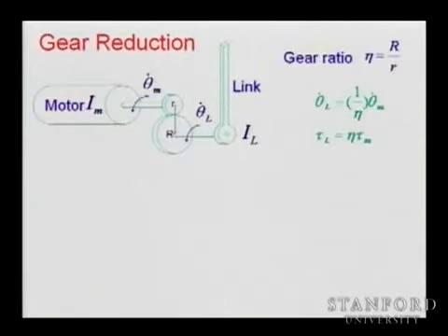How about the torque? Well, as it's written, we have a gear ratio of 2 here. The torque at the link is twice as big as the torque at the motor.